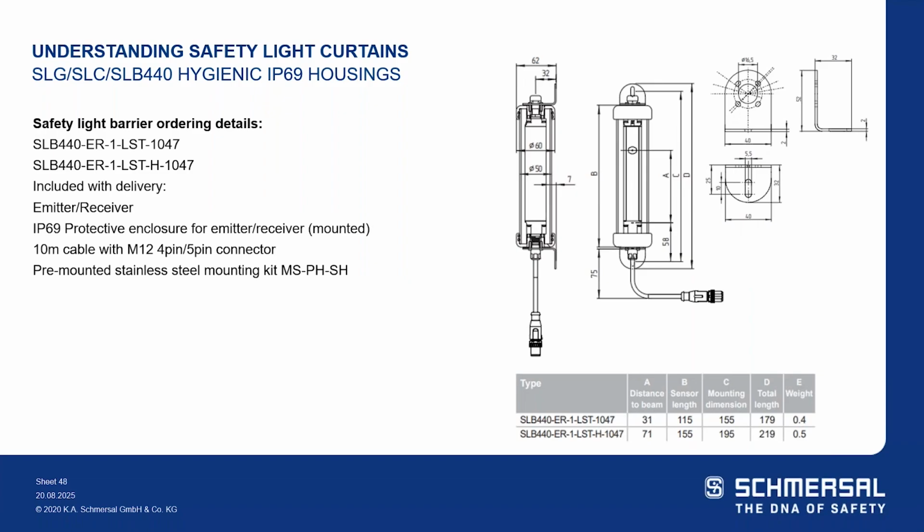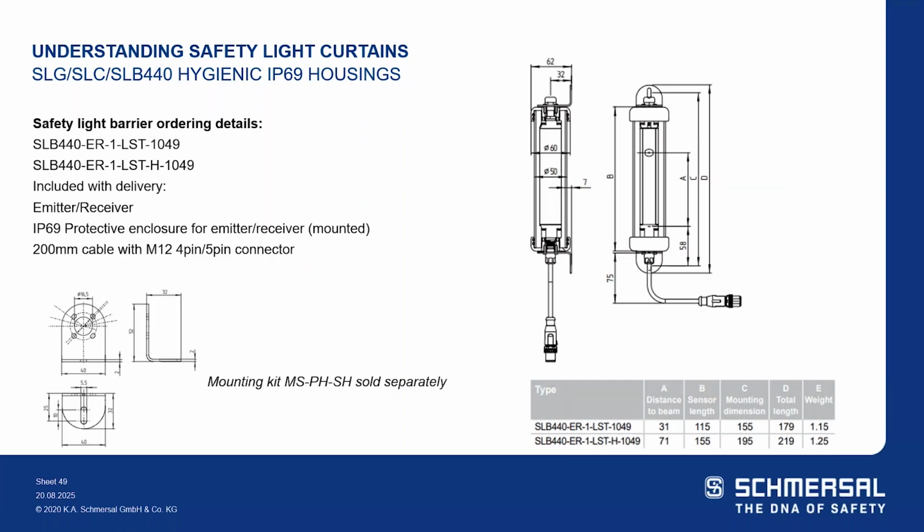So depending upon which version that you get, there's a version here with the 1047 suffix that will have an LST or an LSTH for the high range. And then there's also the 1049 suffix with 200 millimeters of cable with an M12 4-pin connection, where the other one had a longer cable length, but giving you options for the IP69 hygienic housing on the light beam.